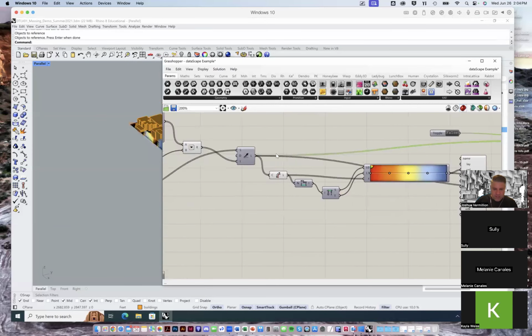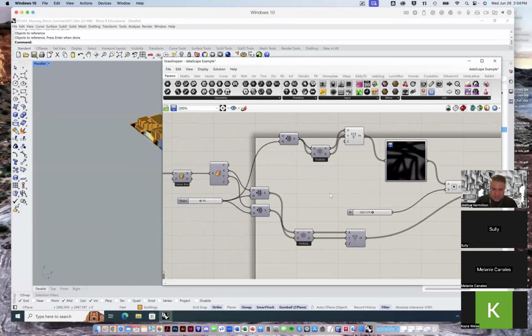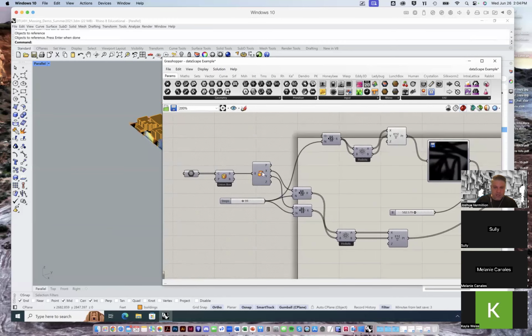So really quickly, without digging too much into this, each of these nodes almost corresponds to hitting one of these tools in the toolbar in Rhino, right? So for instance, if I found a tool here that said draw a bounding box around all the objects I have selected, I'd click that tool, and then in the command line, it would ask me for the ingredients. It would say, select any geometry that you want, and then hit enter when you're done, or right click when done. And then it would actually, as an output, give me a box, right?